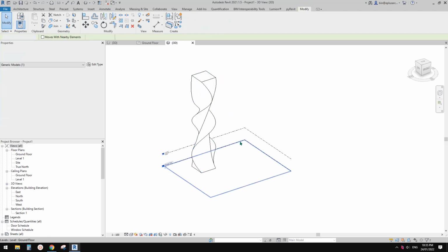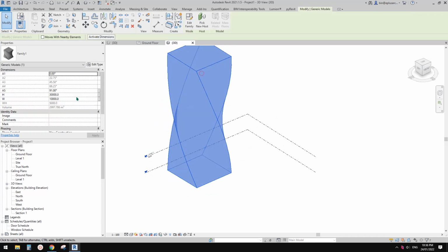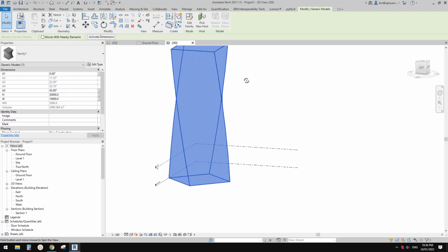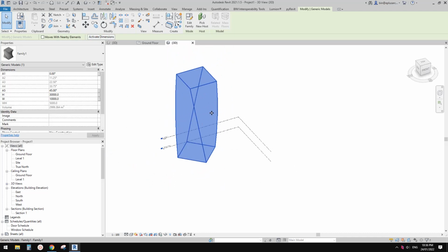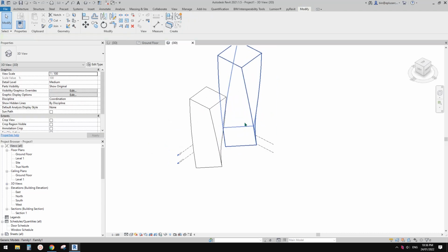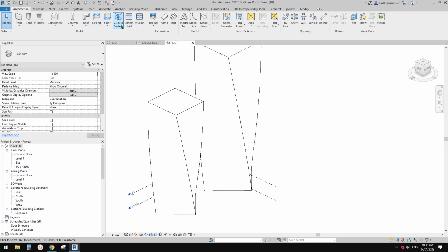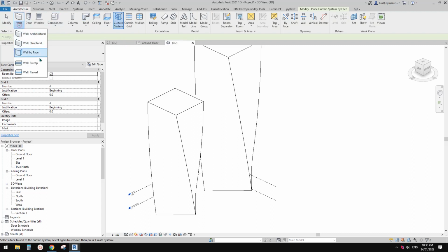So what we can do with this massing is, for example, we can just change the size. Maybe I'll change this one to 91 degree. And then we have this massing, so I'll just 45 degree. Okay, so we have this massing, as something like a building, so you can have different size, 40 meter, so you can have this one 12 meter width, and you can add some curtain wall, not curtain wall, curtain system. I don't think you can create curtain wall.